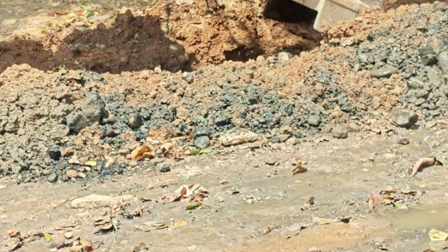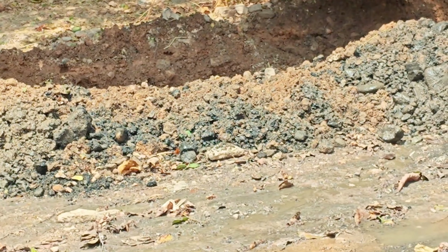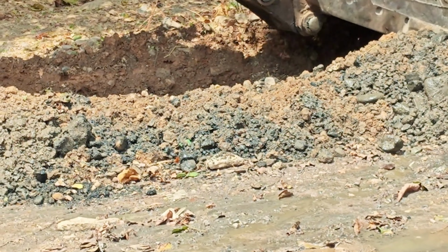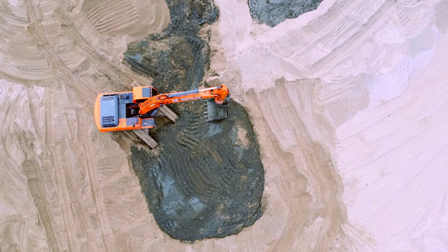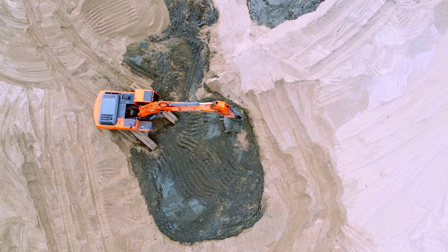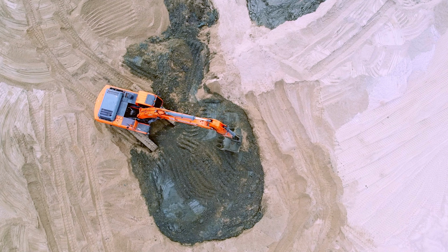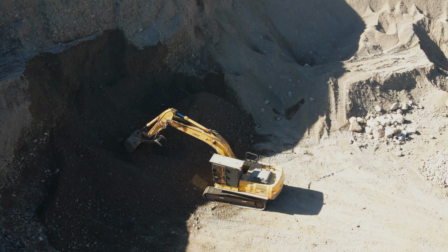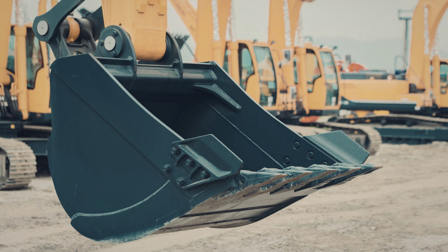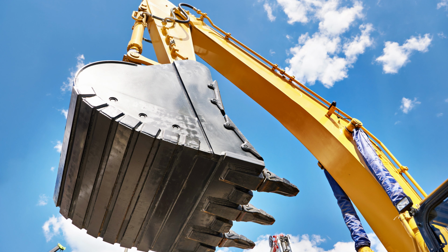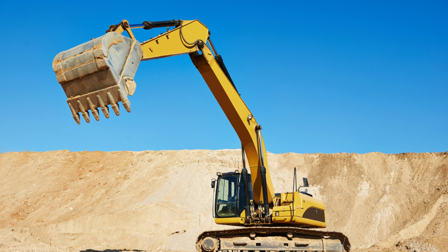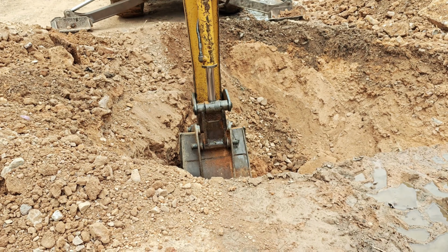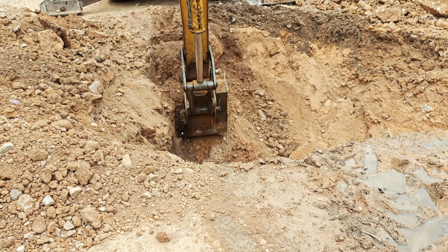Loose sand generally offers lower resistance, allowing the bucket to penetrate more easily. In contrast, cohesive soils, such as clay, provide higher resistance due to the bonding between soil particles. Hard or compacted materials, including rock, create extremely high resistance and therefore require reinforced buckets, stronger teeth, and higher hydraulic forces to excavate effectively. From a dynamics perspective, soil resistance acts as an external load that the excavator must overcome using hydraulic force and the mechanical advantage of its linkage system.